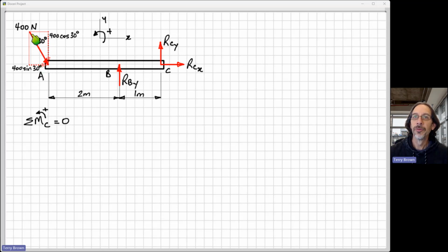Note that I haven't drawn the component of the force up here, because that indicates that its line of action is up here, and if we're calculating moments, it's kind of misleading. Same as if I had put my vertical component out here, because that kind of indicates that it's at a different distance to point C than it really is. So if you're used to drawing your components of forces around the triangle, try and get out of that habit now, and draw them like this instead.